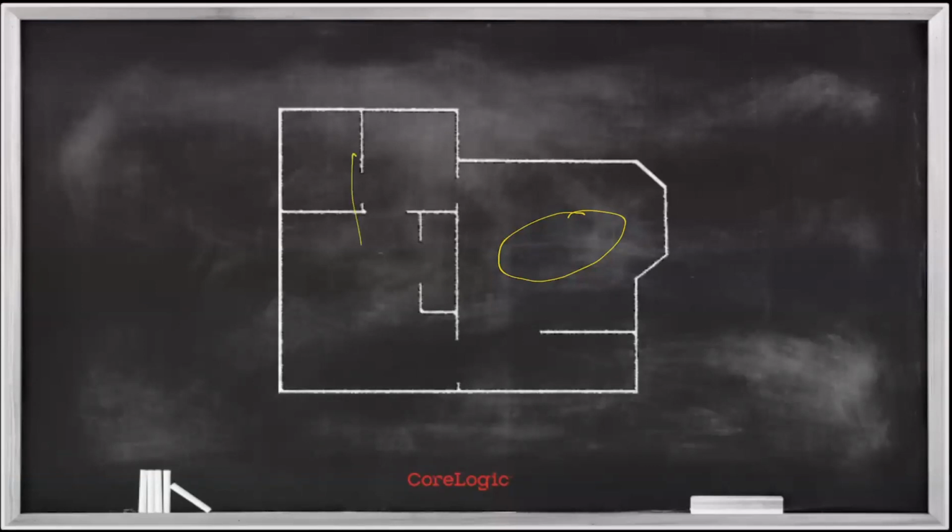And maybe the balance of the space is all carpeting over cement or carpeting over a plywood subfloor over a crawl space, whatever it is, but something a bit more typical where I don't necessarily need to be as aggressive or purposeful in the system that I'm going to apply. And in a case like that, I may choose to break the chambers apart so that I can control the spaces independently, right? So that may be another reason that I would break these into separate drying chambers.